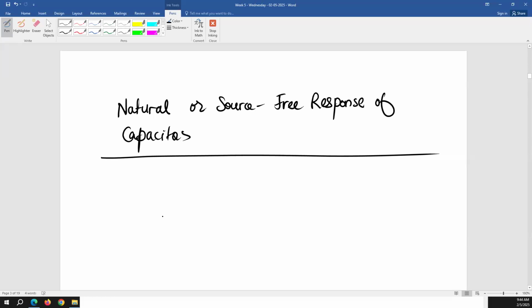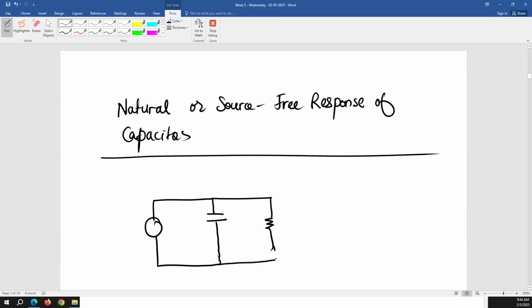So we're going to start with the discussion of a simple circuit with one capacitor and one resistor. It's not a dependent source, it's just energy, because its value does not depend on any other current or voltage flowing in the circuit, right? It's just the energy that it has stored. It starts dissipating that energy if there is no other source available, right? And the important thing is you need to have a closed loop, otherwise it's just going to hold its charge. It's not going to dissipate that charge.